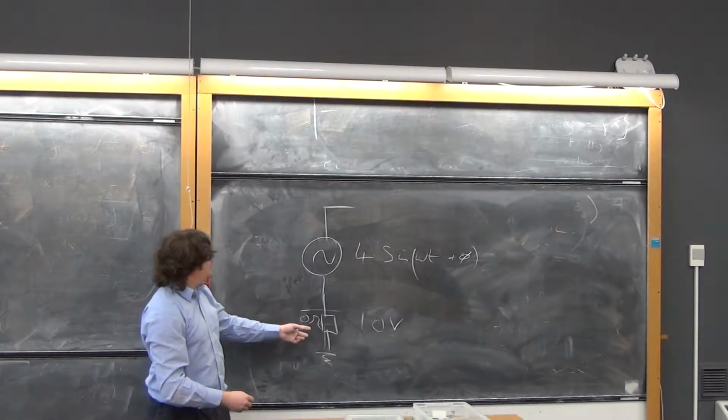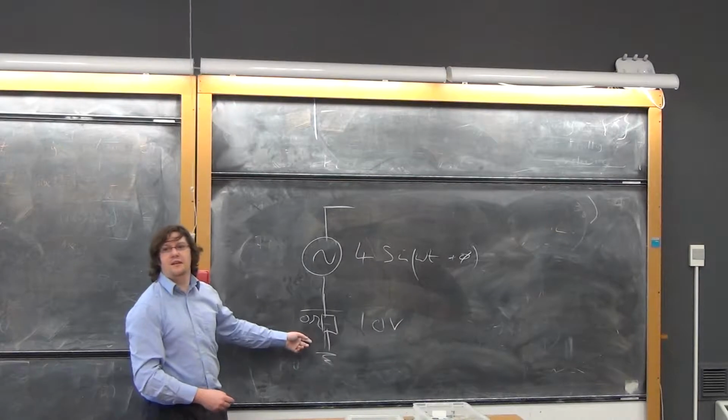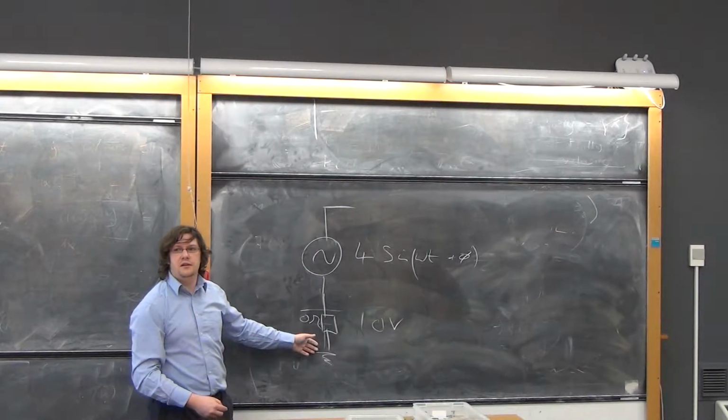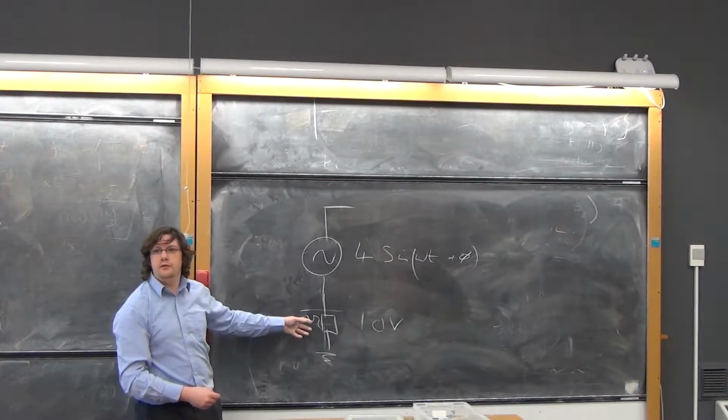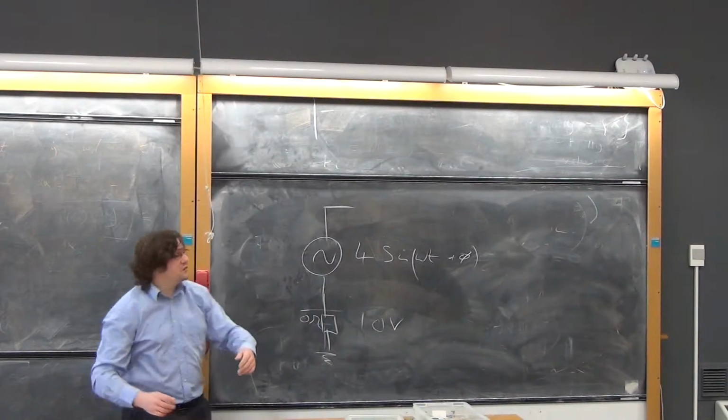But you still have a good current return into your source because this is just a wire with a label. And you can switch off this one and leave yourself with just the DC. So you can do the superposition of the components just by saying all the components are secretly separate. There's no magic involved.